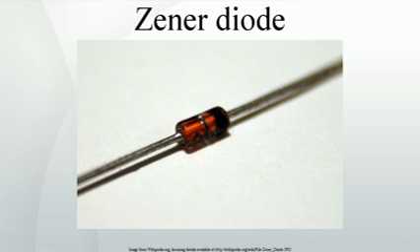By contrast with the conventional device, a reverse-biased Zener diode exhibits a controlled breakdown and allows the current to keep the voltage across the Zener diode close to the Zener breakdown voltage. For example, a diode with a Zener breakdown voltage of 3.2 V exhibits a voltage drop of very nearly 3.2 V across a wide range of reverse currents. The Zener diode is therefore ideal for applications such as the generation of a reference voltage, for example for an amplifier stage, or as a voltage stabilizer for low-current applications.